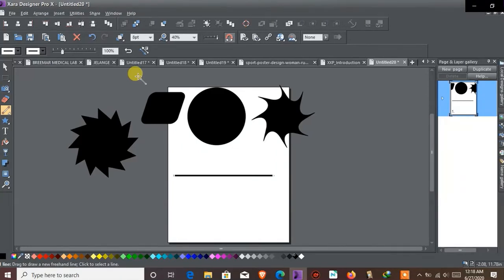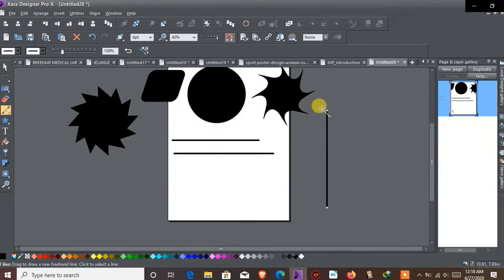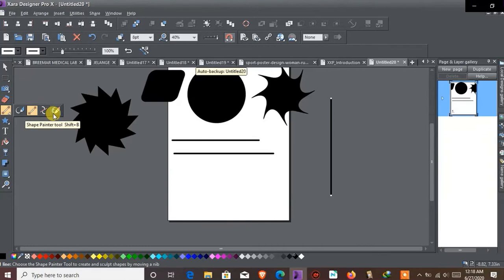So we are going on again. I'll use my tool and draw. Then I'll hold my Control to get a straight line. If I want it horizontal, I hold my Control and we get a straight line. This one is an open shape. It cannot join. This tool is only for straight lines, not to join. It does not meet.